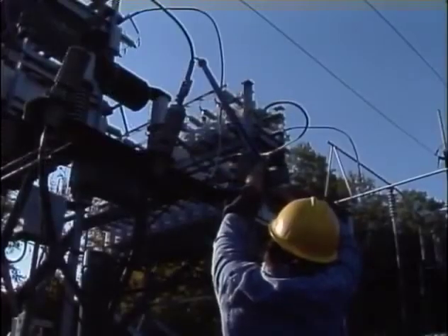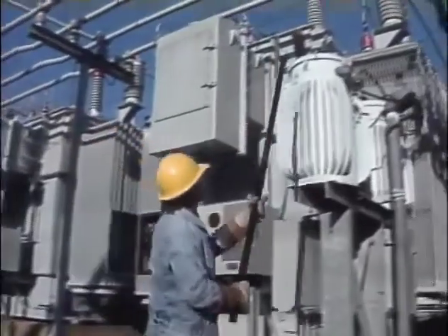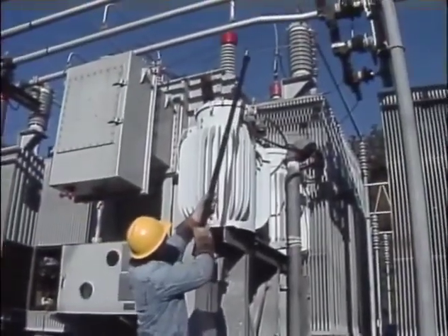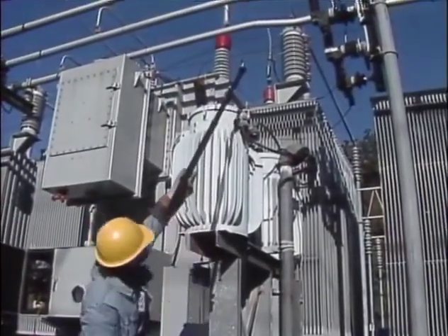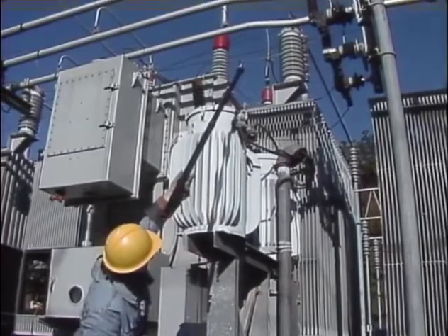After testing the entire bank, the worker rechecks the glow stick on the known live circuit to make sure that the glow stick is still working reliably. Normally, with other substation equipment, the next step would be to ground it. However, with a capacitor bank, it's important to wait a while before grounding the bank. Typically, the waiting period is 5 to 10 minutes, depending on your company's requirements.